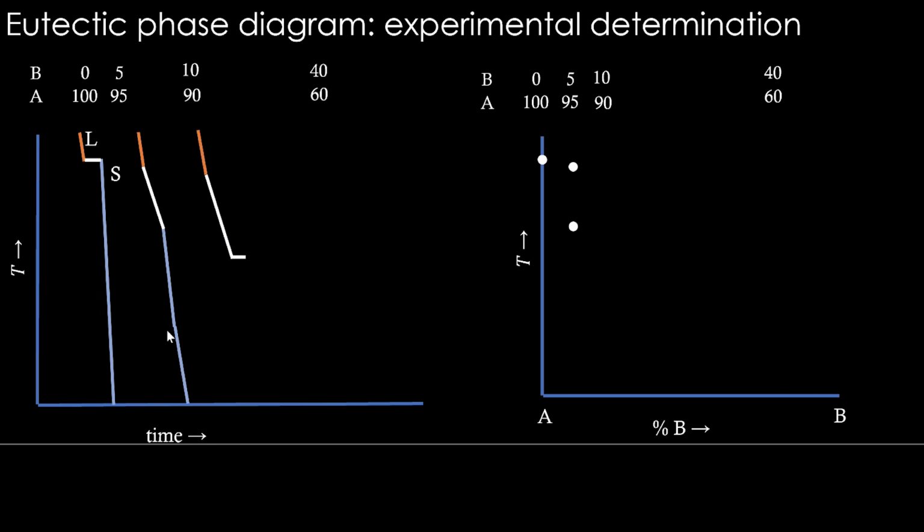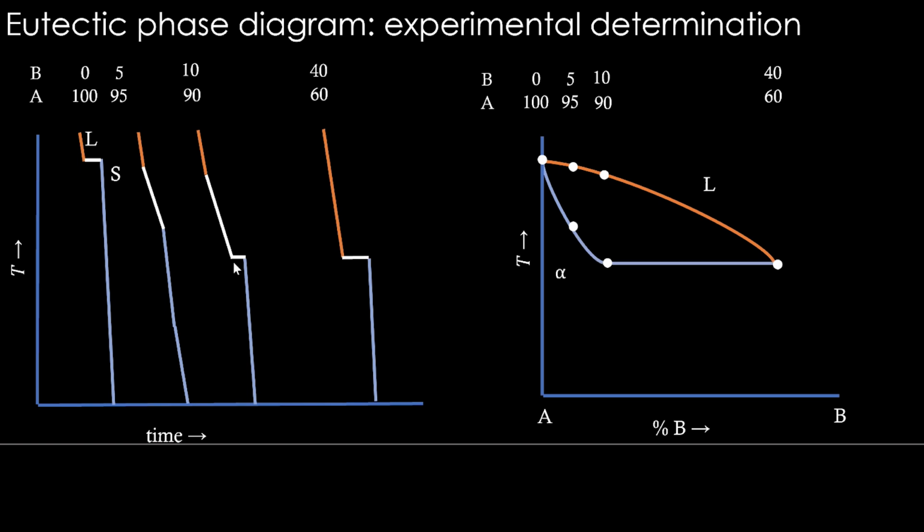So if you see here, this is the composition where the eutectic point may cross. Okay, this is the pro-eutectic phase formation region. Then this is the eutectic transformation region, which will be like a horizontal line. So let's translate these points here. Then things are going to happen at one single temperature as if it is a pure metal. We have seen this idea before. So this is how the eutectic point will look. Joining these lines, we will get liquidus and solidus, and this is the eutectic reaction line. Below that it will be alpha plus beta, above that alpha plus liquid, and this is the alpha region encompassed within the solvus lines. So these points come from the cooling curve method, and this can be repeated to the right hand side also, and a eutectic diagram can be obtained.